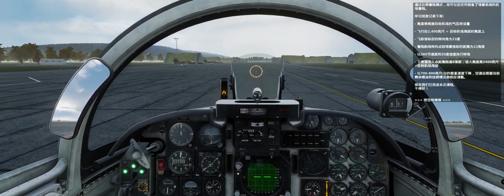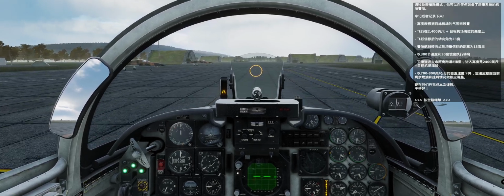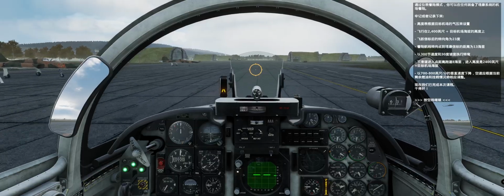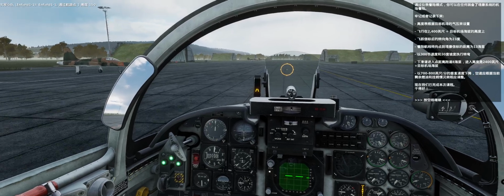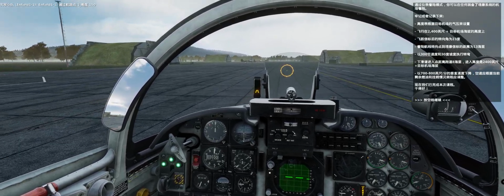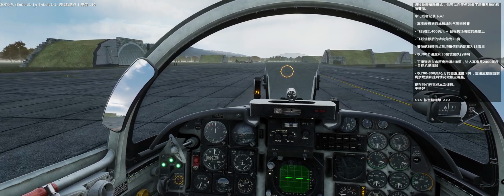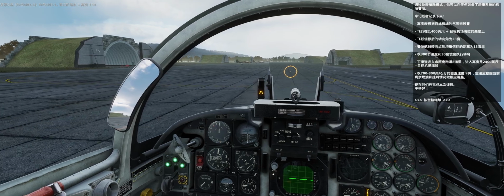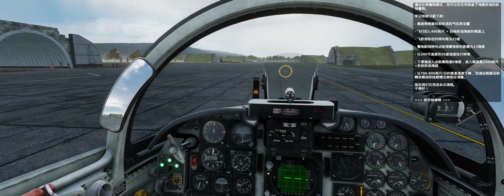Using this instrument landing pad, you can land at any airfield equipped with the TACAN system. Remember or write down: the altimeter is set to the airfield pressure in reference to sea level. Maneuver altitude is 2,400 feet plus altitude of the airfield. Calculated angle of turn after passing the beacon is 23 degrees.